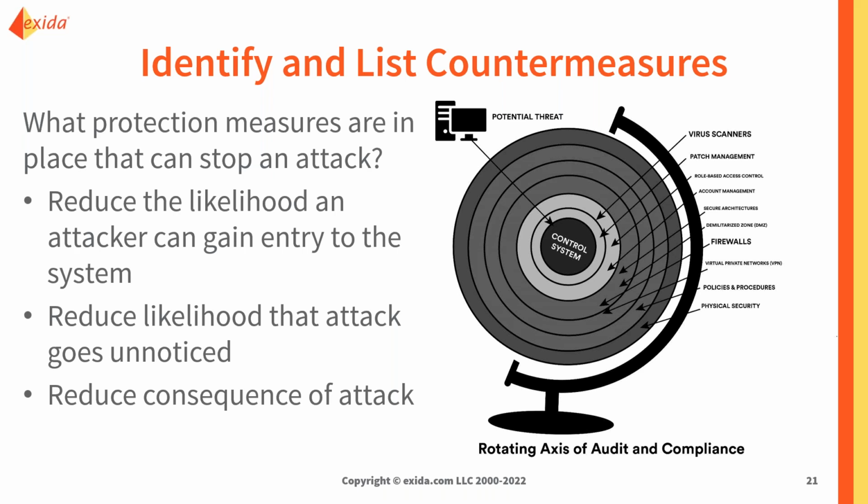Pressure release valves that are going to make the consequence of an overpressure less severe, because it's going to be more likely to be a loss of product or some venting, as opposed to equipment rupture, or dikes or mechanical barriers that prevent environmental releases from being as bad. And so we can think about building these different layers to have more protections between a potential threat and the heart of the control system to, again, be able to reduce that likelihood of getting to that undesirable scenario.